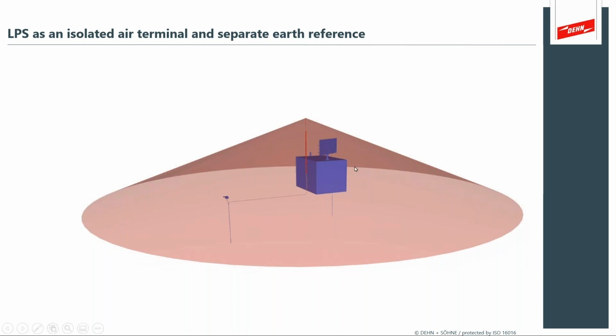And this is a nice illustration showing an air terminal mounted on a structure with isolation from the structure and the victim. So in this case, the critical victim is a radio or a radar that has to be, if I'm flying in the airplane, I want that radar protected, right? So that radar is protected under the fall angle, the angle of protection under that air terminal, and then the down conductor leads it to the ground.